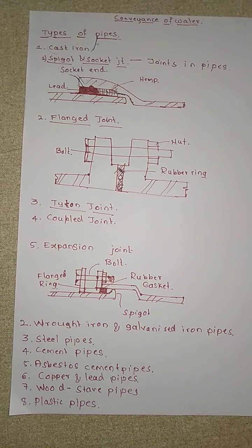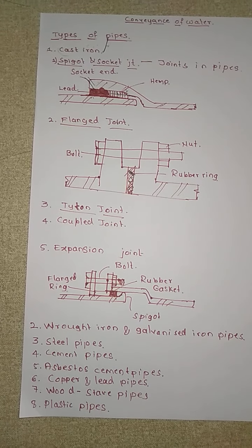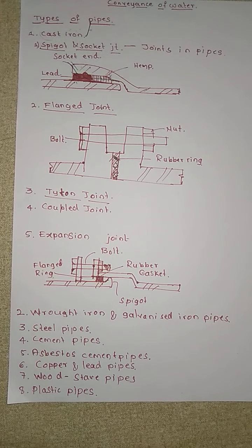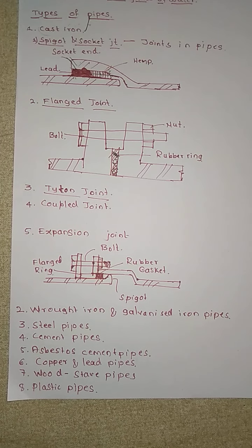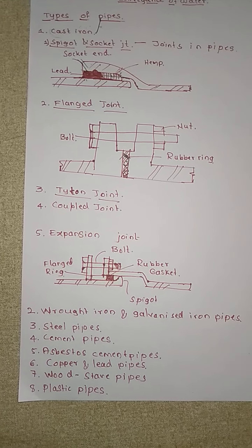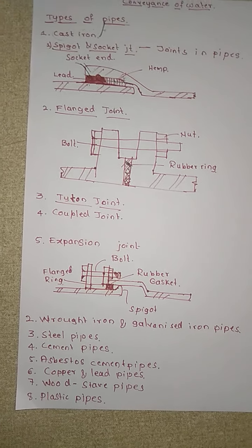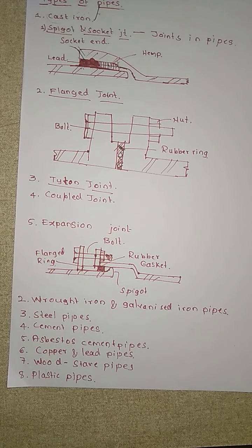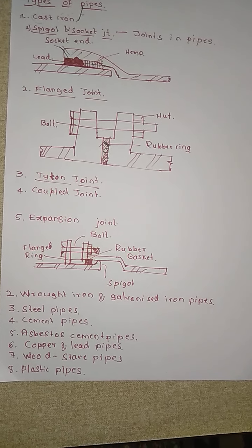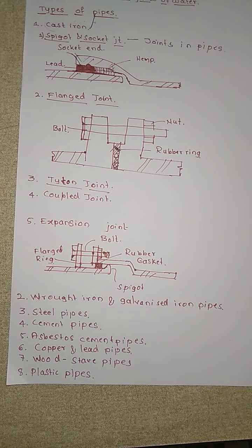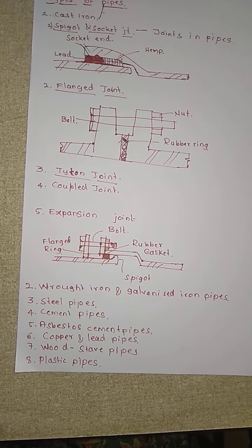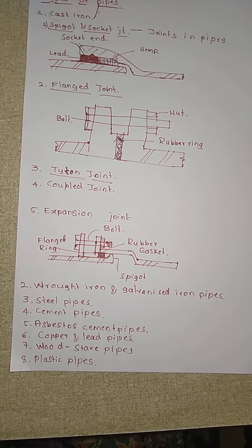These steel pipes are particularly suitable on bridges or under similar conditions where strength and low weight are important. Most steel pipes are connected with the help of the Viking Johnson coupling, as we have seen. The life of these steel pipes under ordinary conditions depends upon the protective coating provided on the external as well as the internal surfaces.